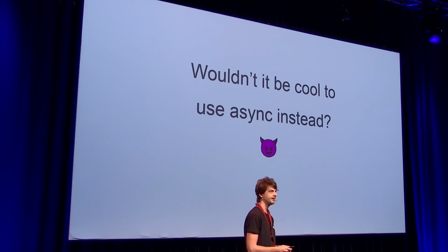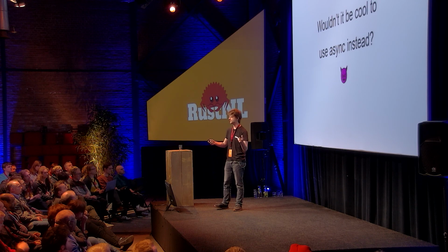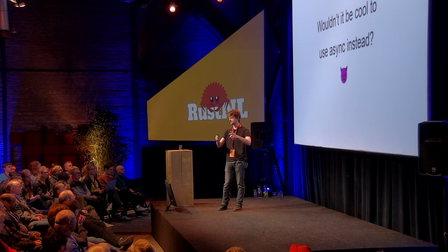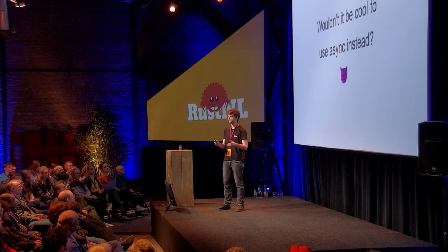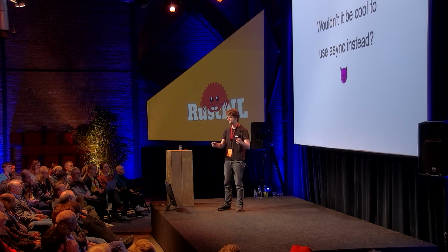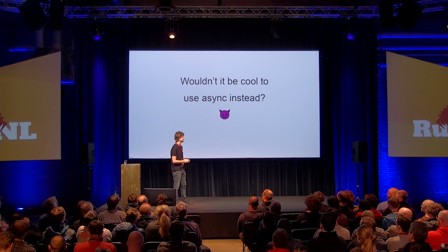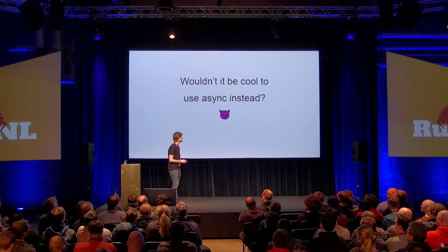So even if the underlying mechanism is very different to RTOS threads, maybe this could give you a similar developer experience. You have tasks where you write straight line code, each task handles one thing, and you have a scheduler, in this case the executor, that makes sure all these tasks get scheduled and run concurrently. So I wondered, hey, let's give this a try.